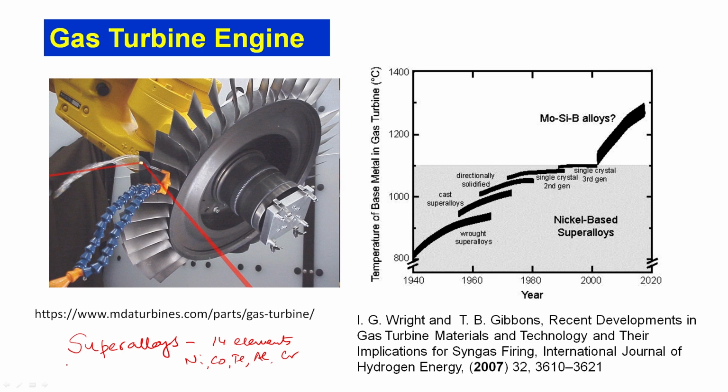The major part of this is the turbine engine, and in the turbine engine the important part is the blades, which are attached on a rotor, as you can see in this picture. As I told you, this rotor rotates at very high RPM, sometimes 60,000 RPM. These blades are rotated by burning fuel, and the fuel burning leads to gas formation. The kinetic energy of these gases impinging on the blades rotates them, but obviously when the fuel is burned at high temperature, the material has to withstand that high temperature. The effects of high temperature are stress, oxidation, corrosion, all kinds of things.